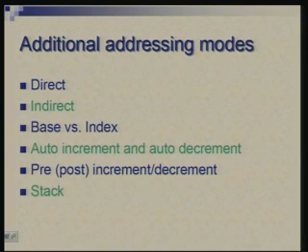I talked about base addressing, where we have a register that can be called the base register, and there is a constant offset which is added to that. In principle, it is similar to PC relative, which I mentioned, but there is another addressing mode which is similar to this, called indexing mode. It is just a matter of interpretation here. The idea once again is that a constant coming from the instruction is added to the contents of a register to get the address.